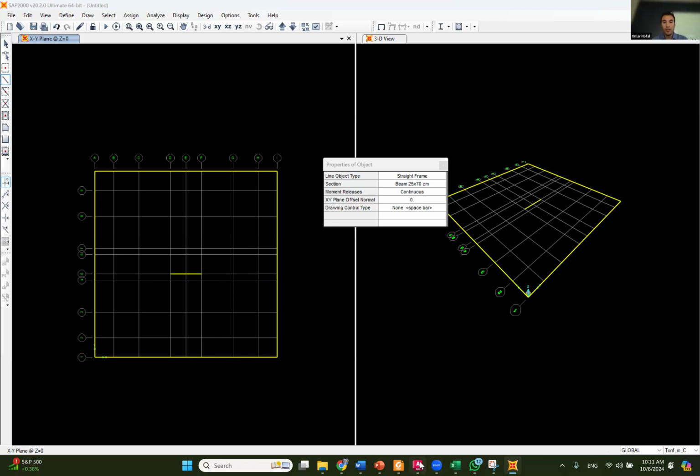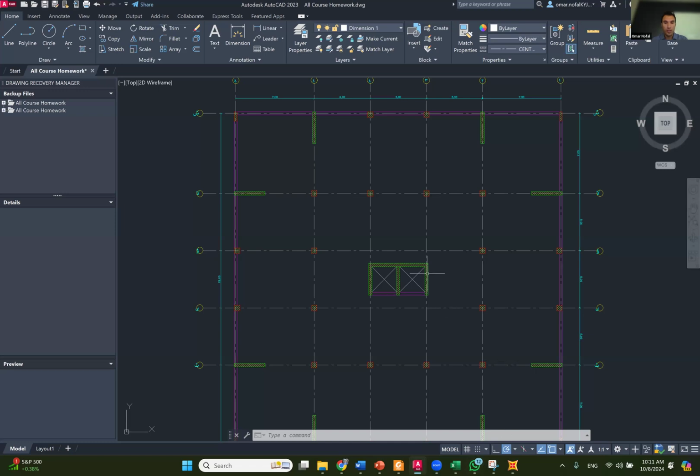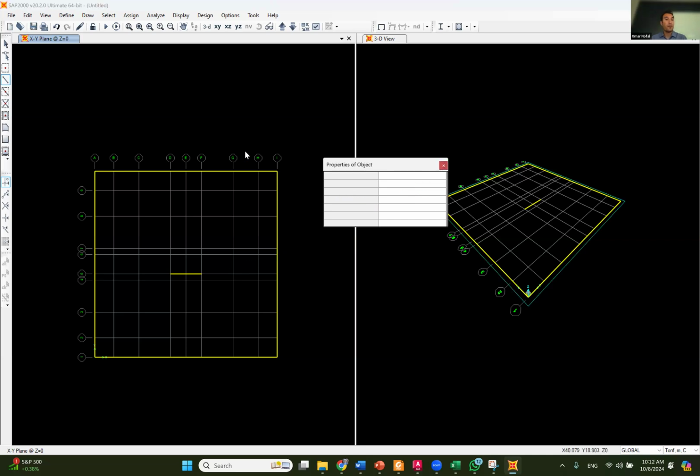for the core system. This is a shear wall. The thing is, this is an elevator, right? You can make shear wall all around, but here there's the elevator door. So the only thing that you can do is a beam on top of this one, which is this beam. This beam is usually bigger than the marginal beam, or stiffer. Okay, I'm gonna keep it the same dimension as the original beam. So I'm done with the beams.